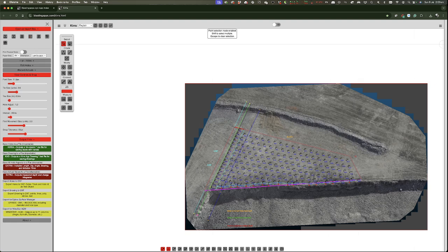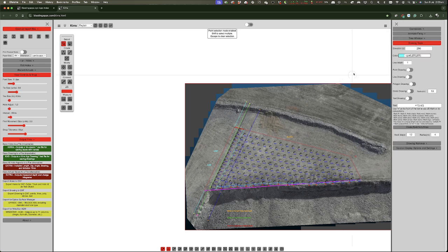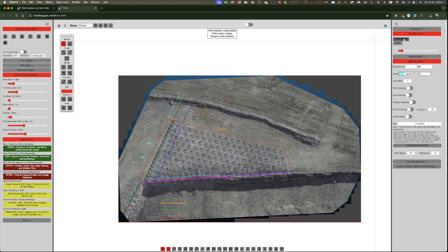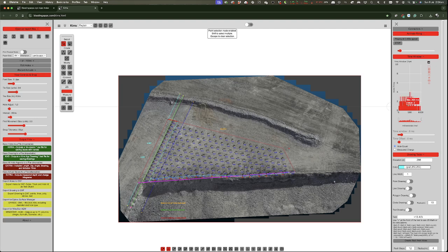There's lots to it. There's even more we haven't touched on this side. Oh yeah, there you go. You probably want to fire it, right? So you've got the animate button here, and we've done a type, so let's animate the blast. We can dial that up a bit faster or slower, or dial it right down really slow, and we've got a time window, so we can see what our timing is and which holes are firing in which windows. If we dial it out like that, so we've got a bit more of a window, we can see these sorts of things.